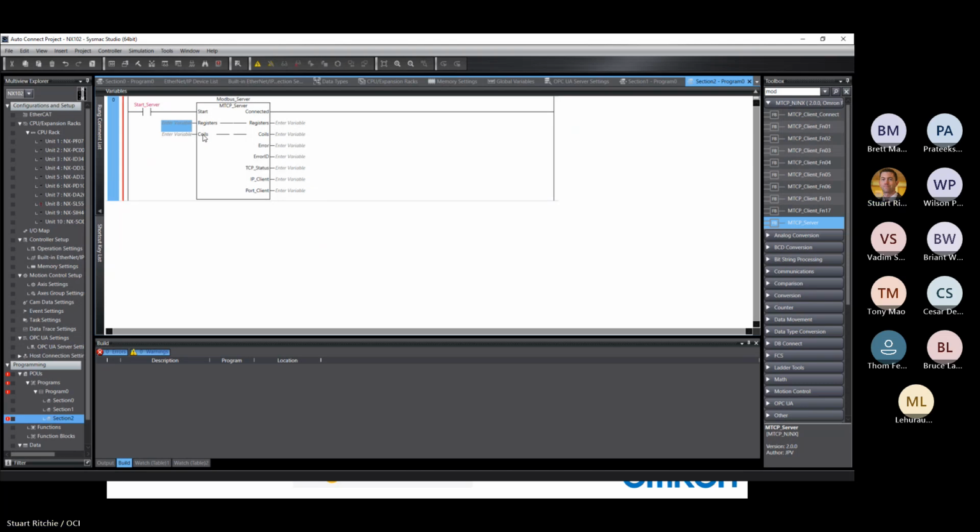So when we do this, index number 1 in our registers, for example, will be the value we respond to address 1 with. This will make a bit more sense once I have a client running on my computer and we're changing data and seeing it update. But it will create the correct data type for us. So I'll call this MB regs for registers, and I'll call this MB coils for coils.